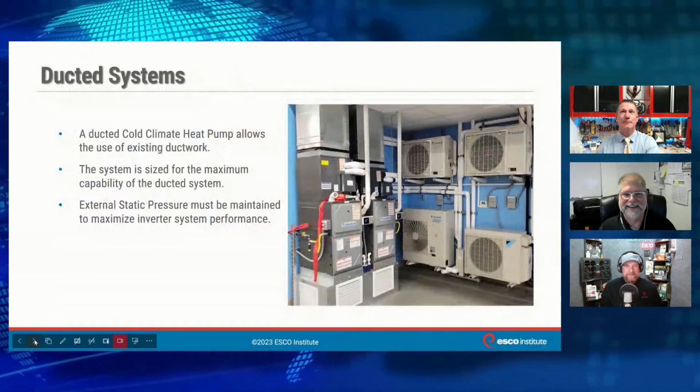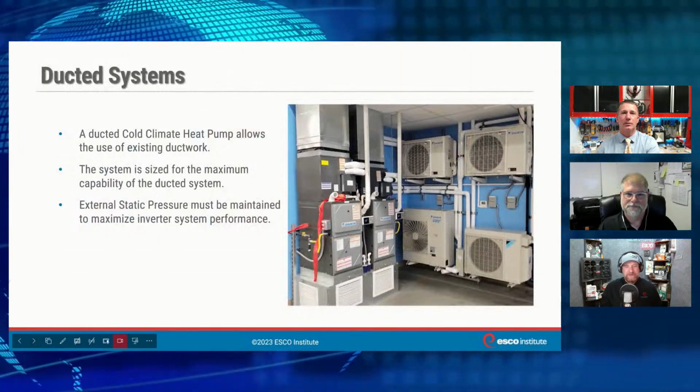One of the things I hear from people all the time is, well, they just don't build equipment like they used to. And I said, well, maybe not. Are you installing it, checking the airflow, checking these other things? They said, well, oh no, we don't have time for that. I said, well, you cannot blame the equipment if you're cutting corners yourself. You first have to control what you can control. If you're not installing it right, we cannot blame the equipment. So we have to first do that first step of doing it right, doing it how it's supposed to be, fixing the airflow.